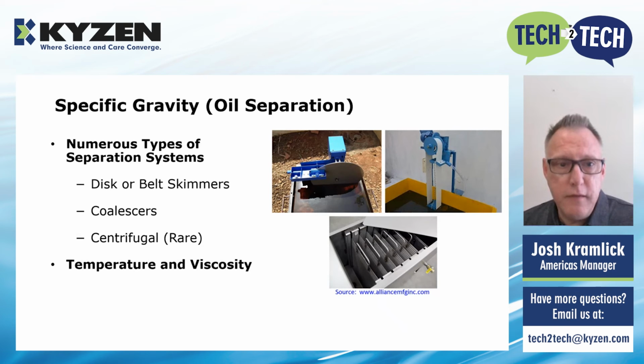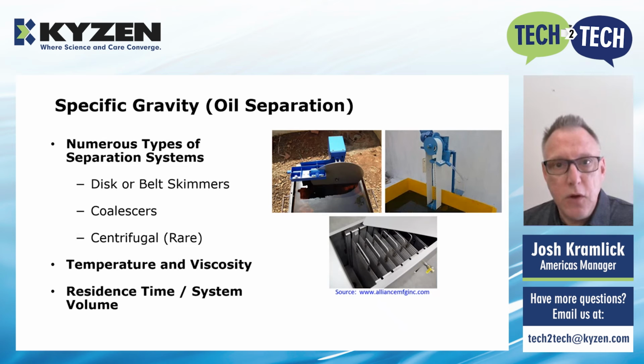Important in all of these are the consideration of temperature and viscosity. A higher temperature aqueous process will lead to lower viscosity oils and less effective skimming. However, if a coalescing system is properly specified, adequate volume and residence time will still allow for good separation.